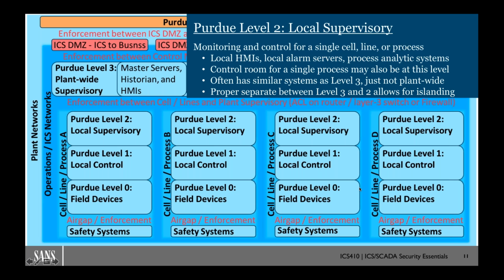When building the security architecture with my customer for this model, we still leverage that demilitarized cloud if it needs to go across their internet links. We build a single firewall rule from that cloud-based DMZ saying that through the firewall, they can only talk to the small number of IP addresses at level 0 at each site. By using the PURDUE levels and these enforcement layers, I can limit communications from that cloud directly down to PURDUE level 0, without the risk of an attacker compromising the cloud and accessing everything else inside of the control network.